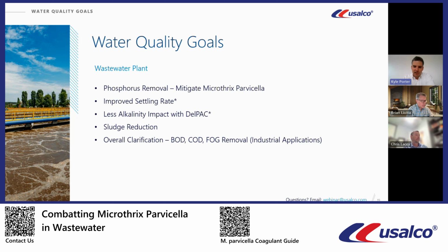And as I mentioned, long-term, the good thing about the polyaluminum chlorides in particular is that we can prevent your filamentous bacteria and also give you a product that's as cost efficient and effective as possible for phosphorus removal. You're still likely going to want to add some more food to prevent that situation and get a more optimal balance for your biology as well. But the good thing is we're basically giving you a comfort blanket, knowing that we'll help prevent that formation even if it ends up being a little low on food relative to microorganisms at certain times of the year.